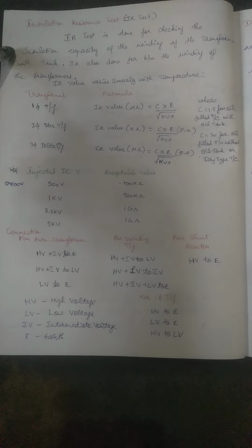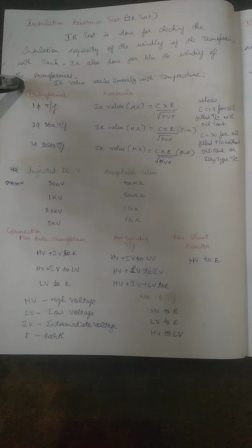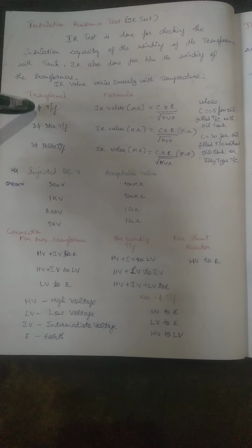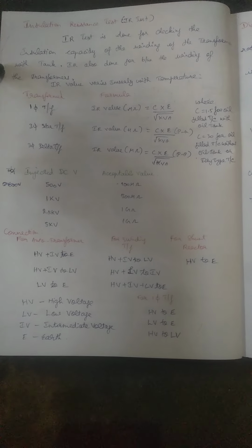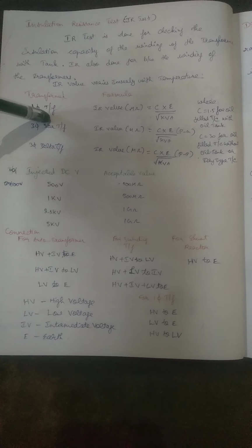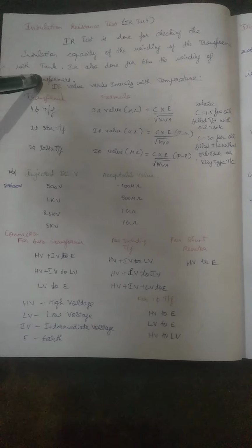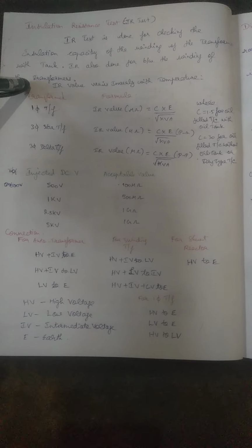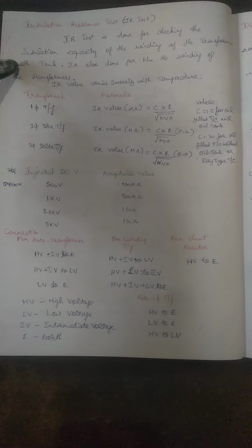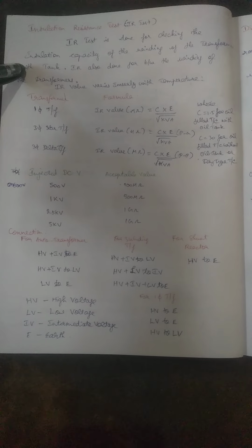And also it is carried out between the windings of the transformer. If it is a three-phase transformer, between phase to phase we will do the insulation resistance test in order to check the capacity of our insulation level.